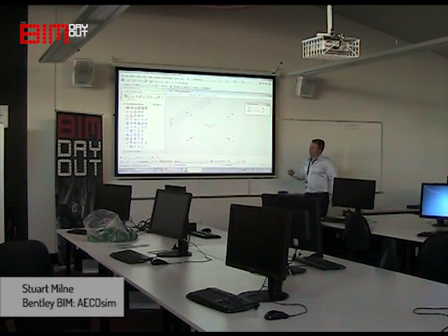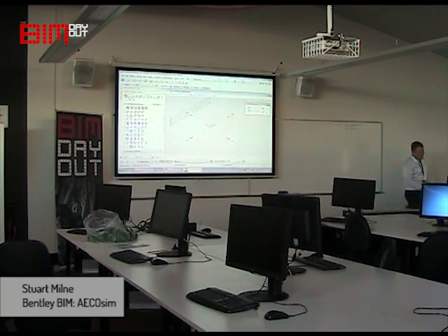So why don't we look at creating a very, very basic rectangular solid. To do that, you'll notice on the left-hand side of your screen, you'll have a menu called Architectural Design Expanded. What we can do is contract that by hitting this arrow, or collapse it. And you'll notice one of the options down here is solid model.